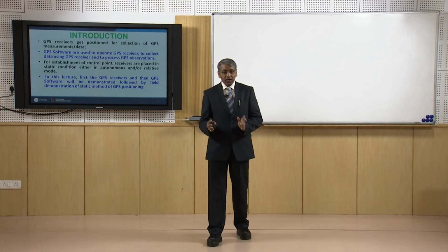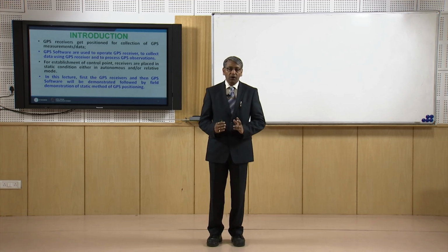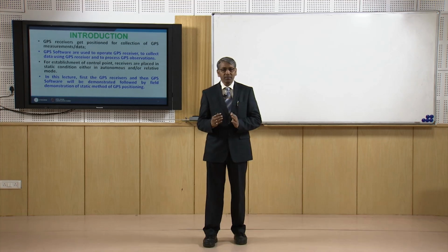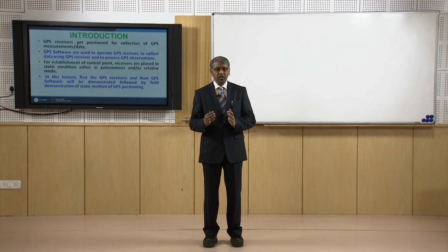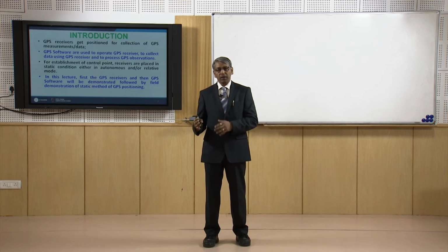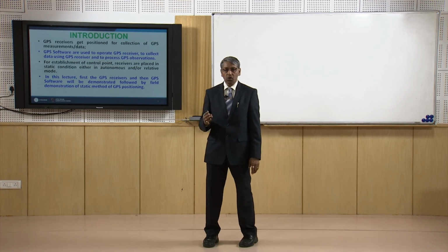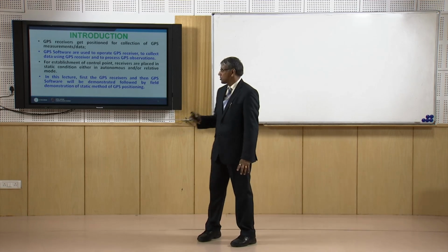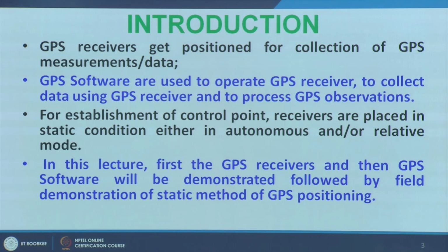And while we are collecting the data for establishment of control point, we make use of the method of static positioning. Either it may be in autonomous condition or it may be in relative condition. So, that type of GPS positioning will be shown in your field demonstration.